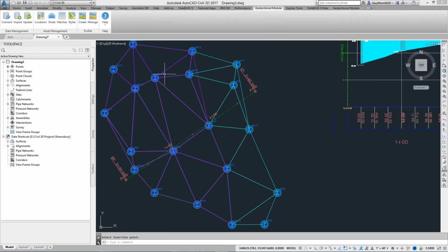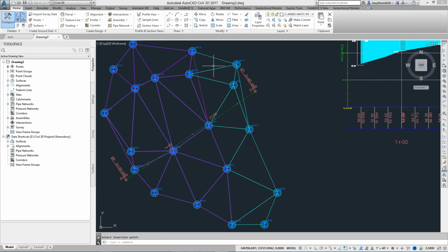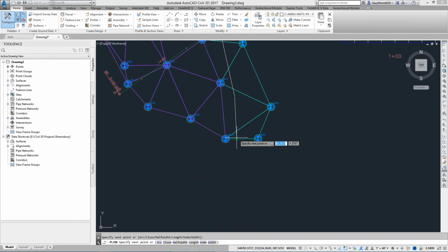So the way we model this, and this is going to be incredibly fast, quick tuition, is to go in and draw a standard AutoCAD polyline. I'm just going to make sure I've got near snap on. I have indeed, and basically just say, well, I think the extent of my gravel probably comes around here somewhere and ends down here. So I just draw a simple polyline.